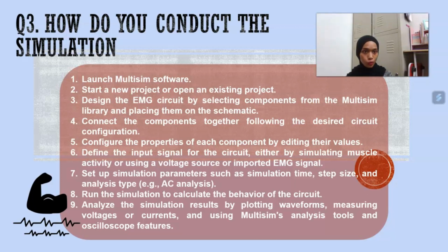I will continue for question 3. How do you conduct the simulation? So, first thing first, to simulate the EMG circuit using Multisim, we begin by launching the software and opening a new project or an existing one. Next, we design our circuit by selecting the necessary components from the Multisim component library and placing them on the schematic.